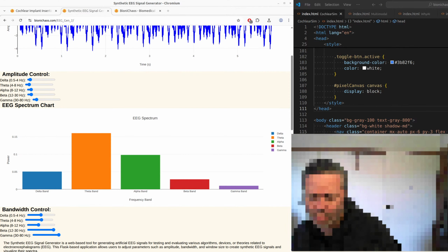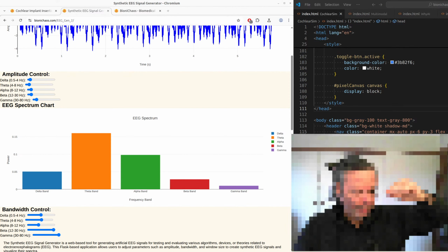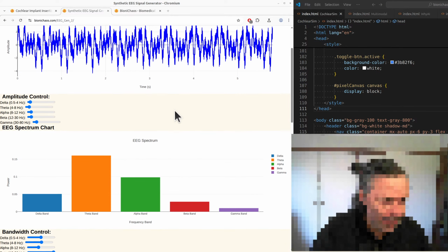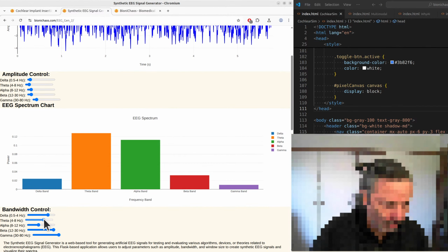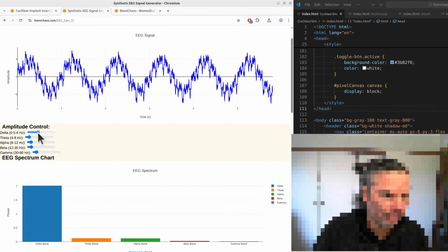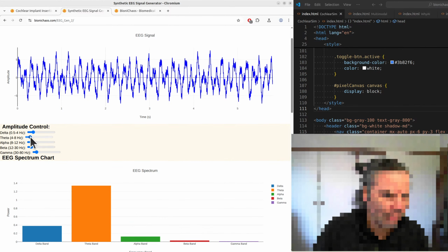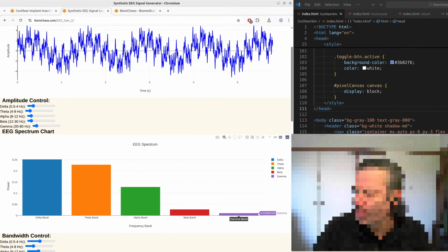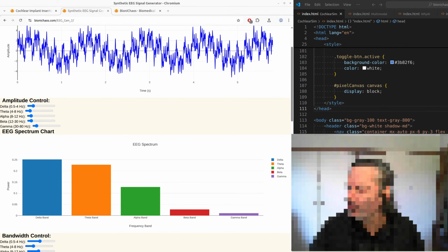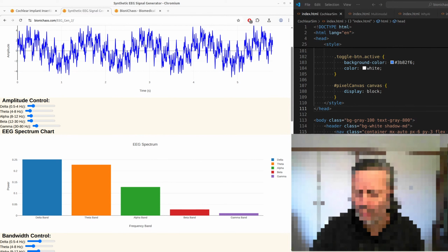Applying the FFT gives you what's called the power spectrum, and that shows the distribution of the signal's power across those different frequency bands, delta, theta, alpha, and so on. And that distribution is important in real EEG, isn't it? Oh, absolutely. Different brain states or activities often show very different power profiles in those specific bands. So seeing that spectrum is key. It sounds like it's built on pretty standard, solid signal processing techniques. What about the tech stack? We know it's Python. Yeah, Python with Flask, which is a popular, lightweight way to build web apps in Python.